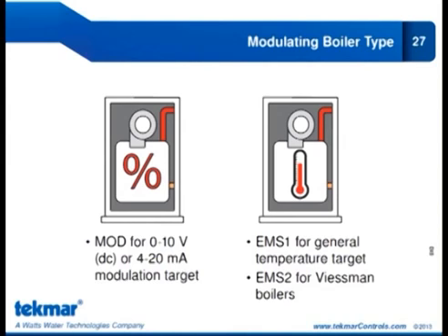So now we can operate multiple Viessmann Vitodens boilers where it outputs a target temperature. Furthermore, we can operate mixed plants. You can have a single stage and a 2-stage boiler, say a Lochinvar Knight and a Viessmann Vitodens. So now you're combining different types of boilers, not just condensing, non-condensing, but different types of gas trains.